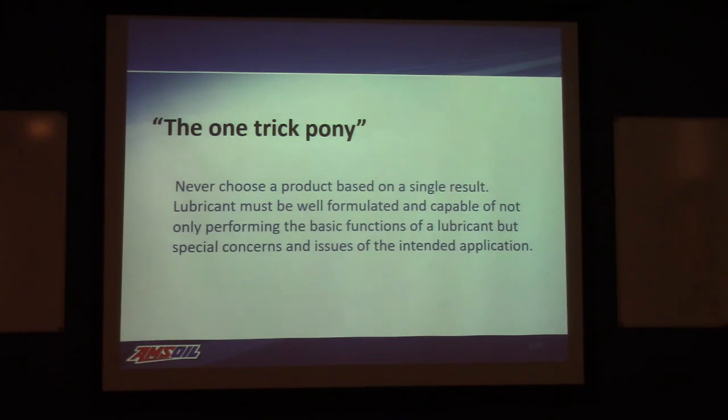For example, a lot of anti-wear additives have an affinity to surface. All right? You get a lot of surface in the engine and it just goes in and plates out on it. Well, you got a slug of it in the oil that you formulated. Now somebody comes in and puts 3 or 4 times as much in there. Detergents have an affinity to surface too.